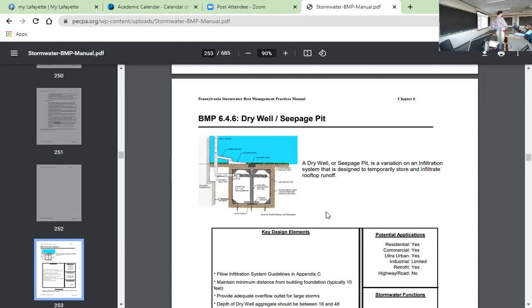Okay. The 2-year storm isn't the storm that happens every 2 years. It's the storm that has a 50-50 shot of occurring every time it rains. What they want you to do is you have pre-development and post-development. You're going to create more storm water after you do your development post than pre. With me so far? You're looking at the 2-year storm. The difference between the 2-year post-development and the 2-year pre-development is what these are for.